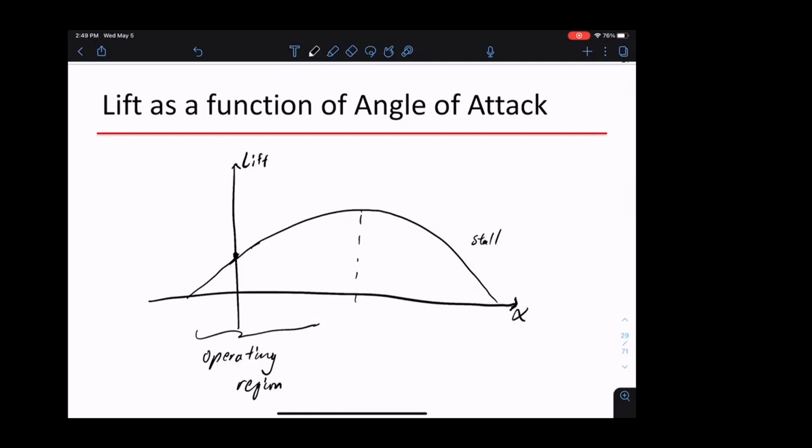This torque has to go somewhere. When connected to the grid, this is electric power going to the grid. But if you disconnect from the grid and you have all this power, it has to go somewhere, and your turbine may fail. So your turbine can fail if you have too much power and the power doesn't have somewhere to go.